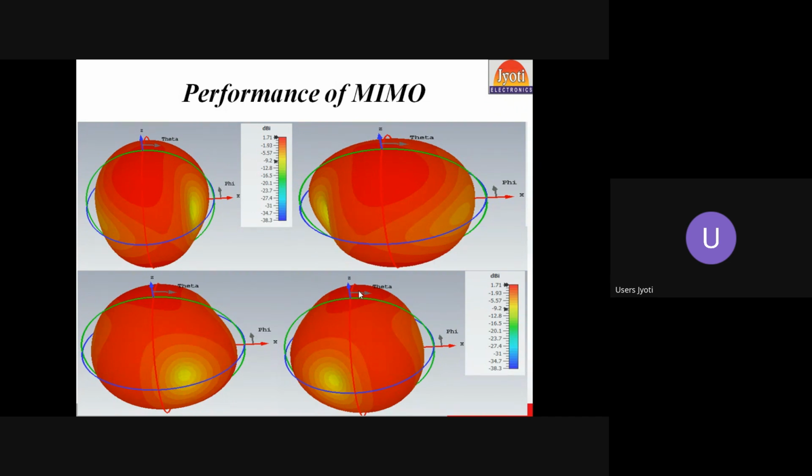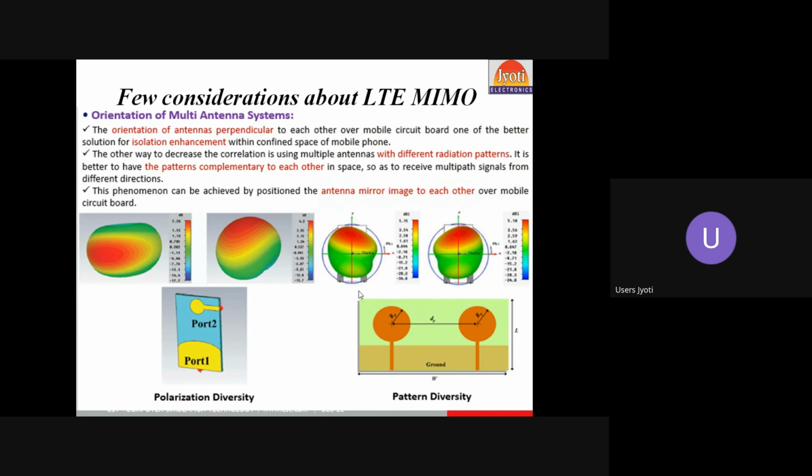Here we can see the radiation pattern. The red part is showing the radiation pattern in space. Mostly 90% of it is red, so that means our antenna is good enough at radiating in all directions, like an omnidirectional antenna. Particularly, the MIMO antenna is good for omnidirectional and all-direction propagation and for the receiver antenna. Here you can see the radiation pattern of the first and second antenna.